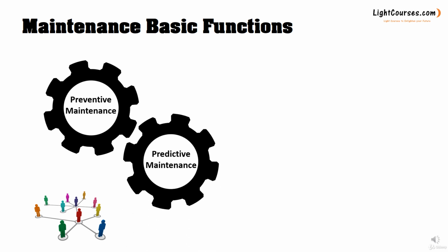When it comes to predictive maintenance, it's the same case as preventive maintenance. So these kind of activities, predictive maintenance activities, which is related to vibration analysis, for example, or oil analysis, or first level of inspection, all these activities have to have someone to take care of. So in some organizations, there is a dedicated team who is supposed to be in charge of designing, planning, and executing the predictive maintenance activities. And in some other organizations, one team could be in charge of 2 or 3 functions together.